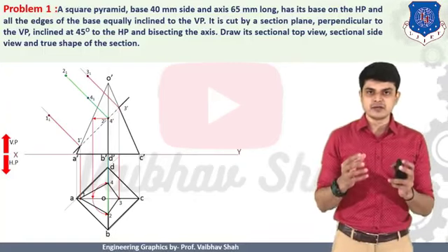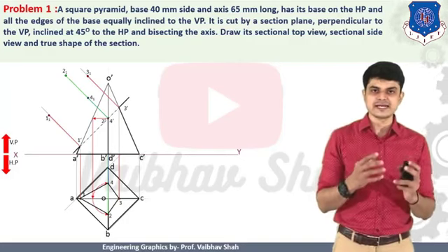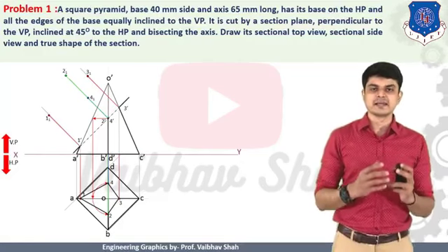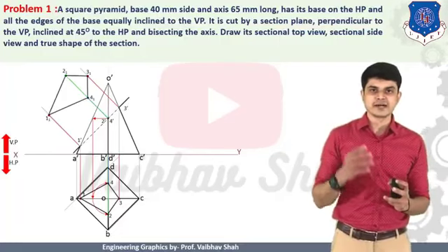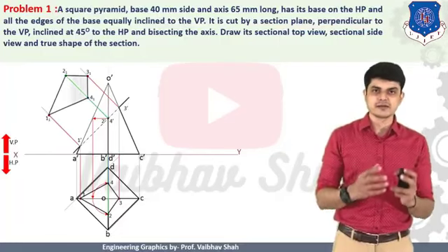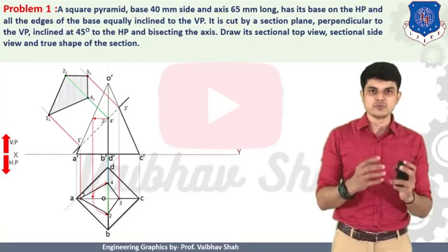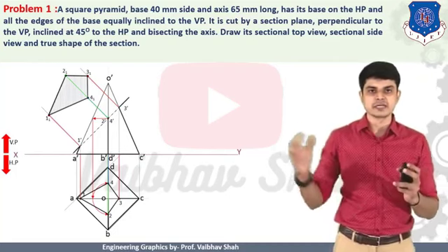After getting 11, 21, 31 and 41, these are the end points of your true shape of section. You should simply connect these points by a straight dark line. So let us connect these points by a straight dark line. So this is nothing but a true shape of section generated while we try to move our object from 90 degree or perpendicular direction from your cutting plane.